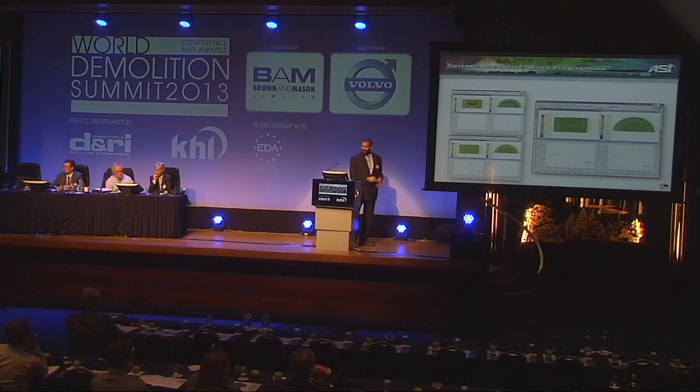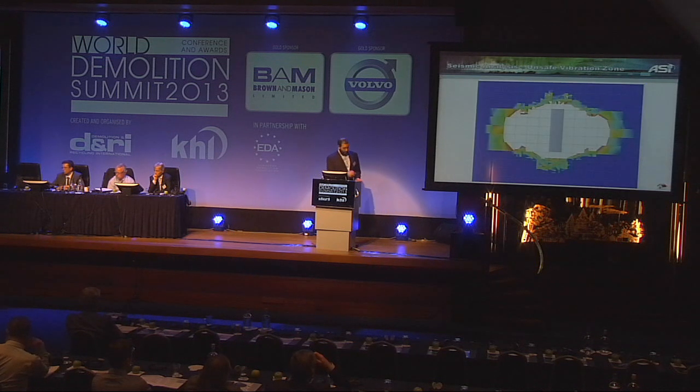Here it goes finally. So this is the vibration propagating through the soil. And we can measure the velocities at different locations here, the chart down below. If you hit play one more time, the charts down below give the maximum vibration at different distances from the structure. So we can say, okay, this is the maximum vibration at this point, and this is the maximum vibration at that point. So this is the kind of thing that you can do if you have sensitive structures, we can create a chart like that.